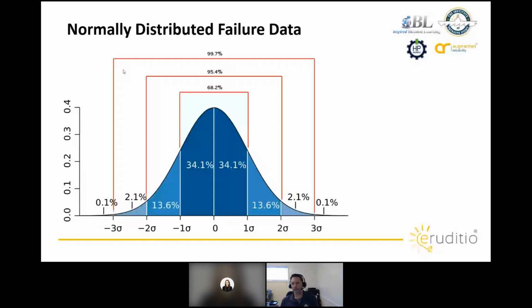If we're looking at, assuming we have a good logistical support system, meaning we have all the right parts and tools and everything on hand, then mean active maintenance time is probably a better measure, because that includes both preventative and corrective actions that we're performing on the equipment. And that really looks at, when we have the equipment down, how well are we executing against it.